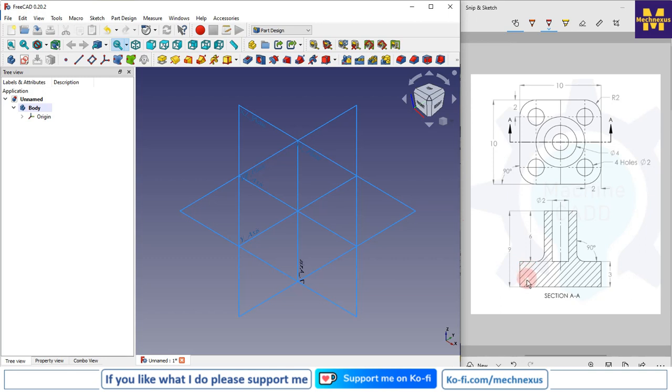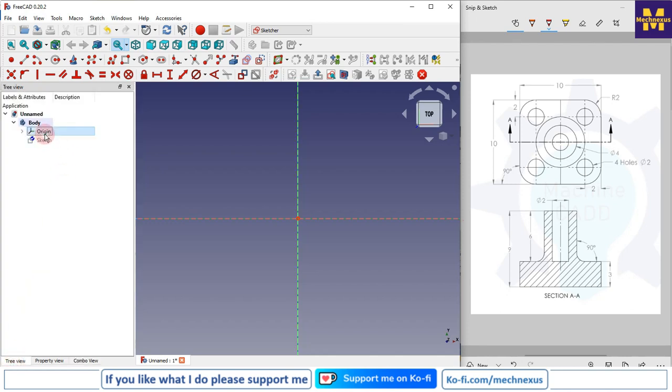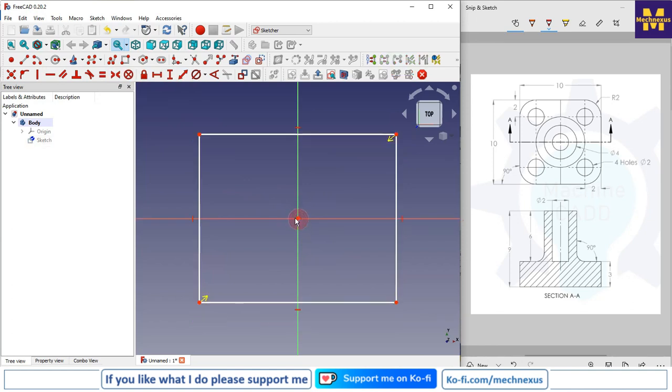So if we see our part, first we will make this boss, which is 10 mm by 10 mm. For this we will select this XY top plane and create a sketch, and I will go to the tree view and turn on this origin plane. Now I will select the rectangle and draw it, and from here I will select the symmetric constraint, and I will select these 2 points and the center point.